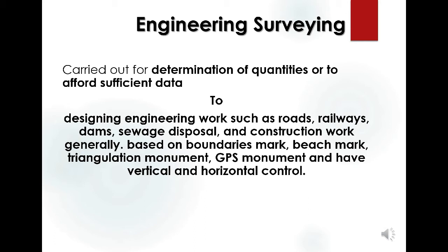Engineering surveyors will use a wide range of instruments to assist them with their on-site work. The most common of these will be the total station, GPS and dumpy level or digital level. Once all the survey data has been recorded, the engineering surveyor will return to the office to process the data, complete calculations and finally complete the as-built documentation. The as-built documentation may be presented on a drawing, spreadsheet or a combination of both.